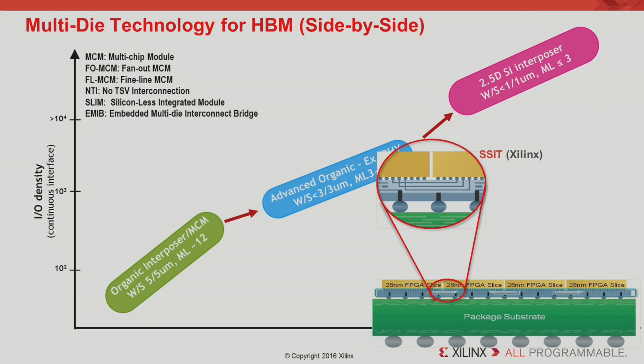And silicon interposer is actually the one in production today. From the Xilinx perspective, though not for HPM but for die partitioning, we have used this. We are already in production with our second generation of products and ready to sample the third. So silicon interposer is a platform where you don't really have to worry about the interconnection density. Any older generation technologies such as 90 nanometer or 65 nanometer could satisfy the interconnection for HPM.